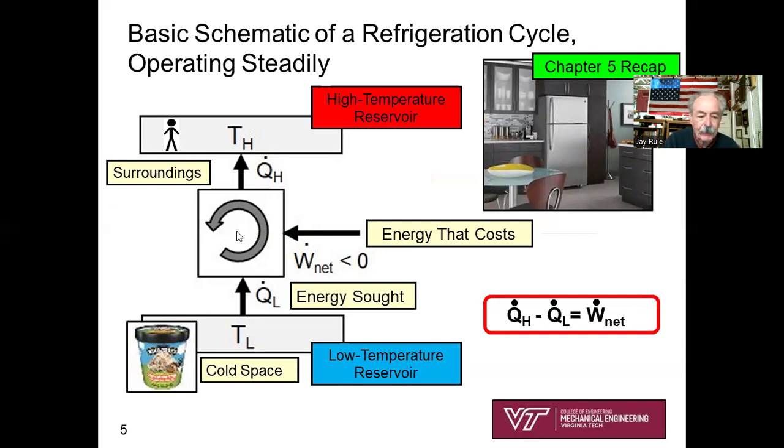So it's a system operating in a cycle. Look at my arrow. My block arrow is going counterclockwise. That means that net power is required to run this cycle. And the result is it enables us to transfer heat from cold, I call it TL, textbook calls it TC, up to hot, TH.